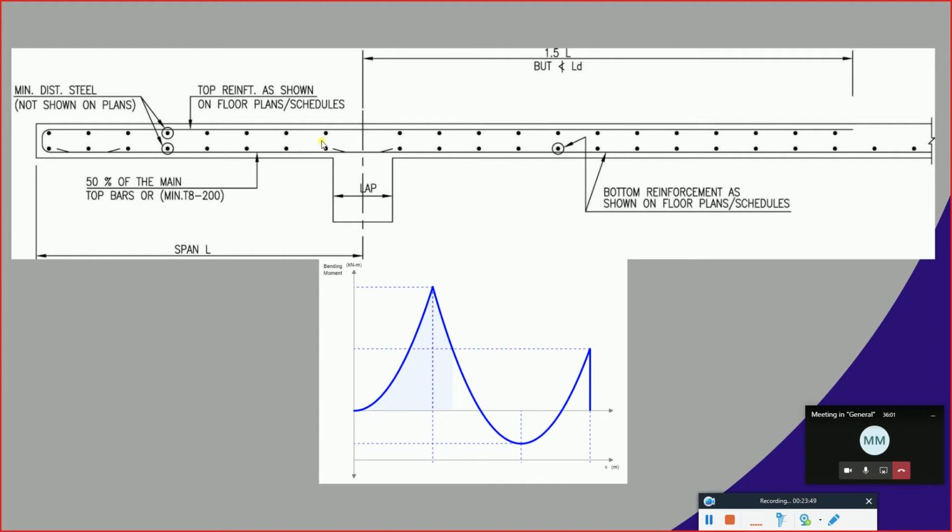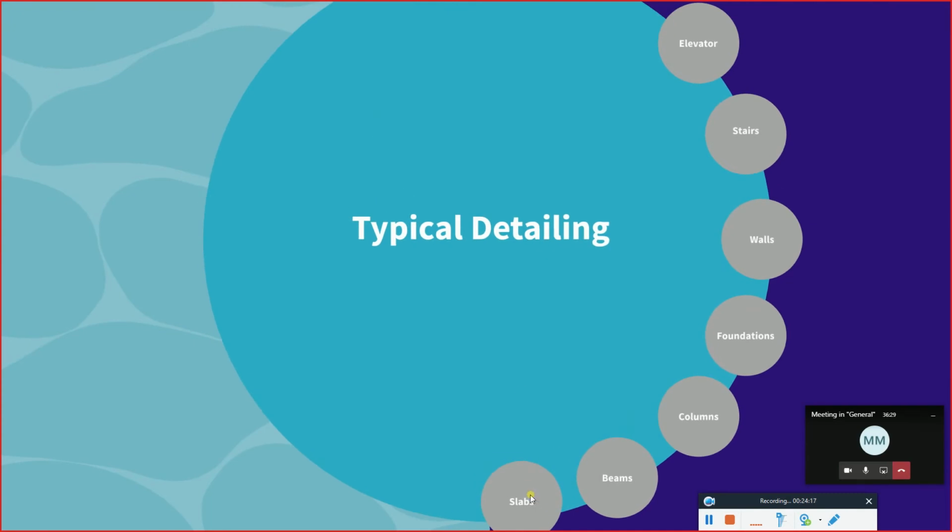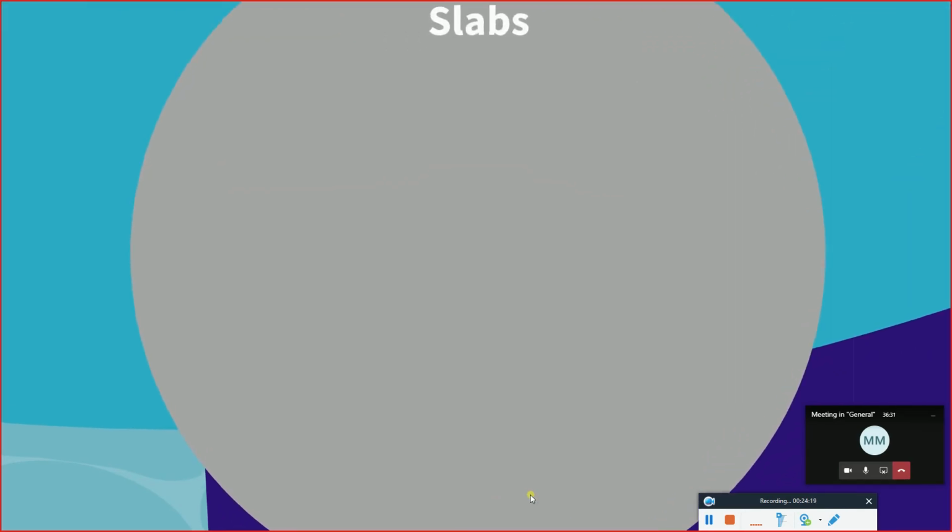So if you can see, we agreed that for the bottom reinforcement it will go from the beginning to the end. We don't stop even if there is no positive bending moment here. You notice that we are supplying bottom reinforcement here. Okay. Now since the bending moment says I have top bending moment in this particular region for a cantilever, we supply the negative bending moment reinforcement. Okay. So one thing that you need to know, before finishing the slabs, one thing that you need to know, okay,